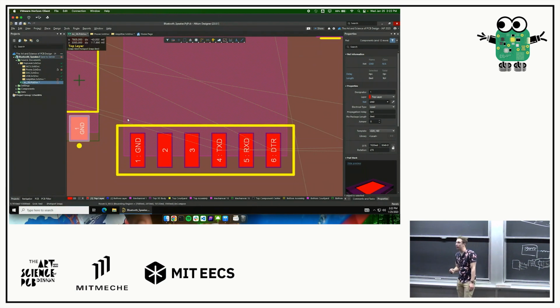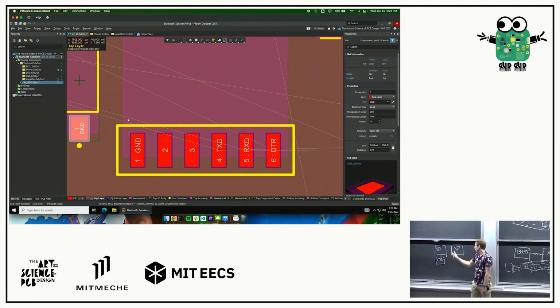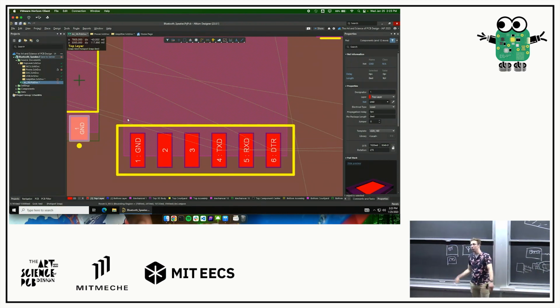let's say we're looking at the microcontroller that we have on our board. It's an ESP32, and it's got that Bluetooth modem, and then there's a CPU next to it, and then there's an antenna over here, right? The symbol for an antenna looks like this. Let's say we have all this stuff going on. We want the antenna to be nice and isolated from the rest of the system, right? Because otherwise, all the noise from our CPU, going beep, boop, boop, boop, beep, beep, will get into our antenna, and it'll make it really hard to receive Bluetooth, right? We're going to have a bunch of noise that couples over through here.